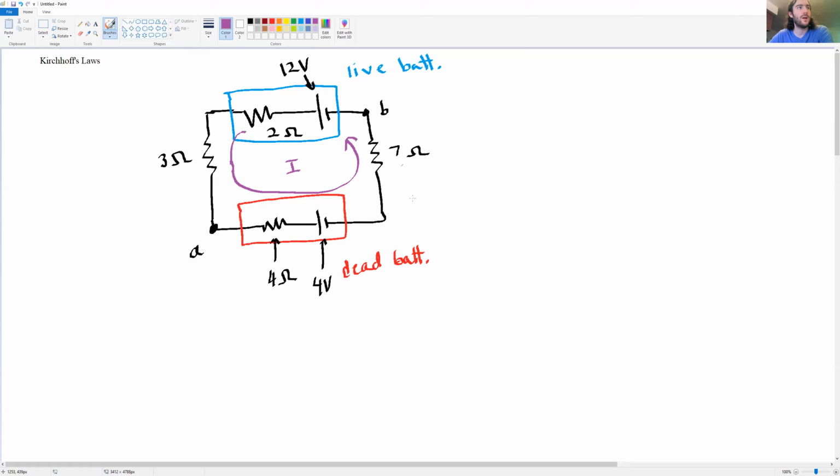So if you're ever doing a problem using Kirchhoff's laws and you happen to label a current in a certain way and you calculate a negative answer, don't panic, leave it as is, change nothing, okay? You've gotten a negative answer, it's just a sign. It does not change the physics at all, okay?